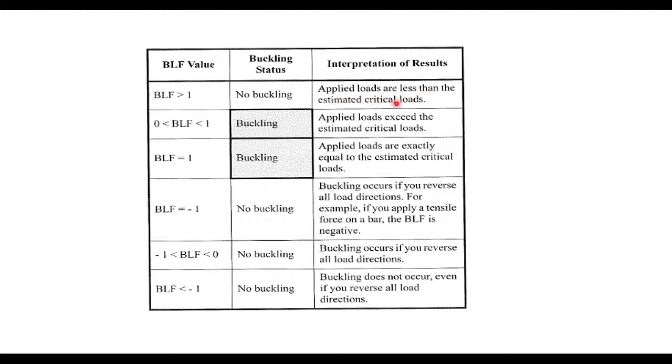So if you get a buckling load factor greater than 1, your model is satisfying the buckling conditions and is not going to buckle. If it is between 0 and 1, then definitely your component will buckle, because it exceeds the critical loads. If it is equal to 1, the critical load and the applied load are the same, and then it is definitely going to buckle.